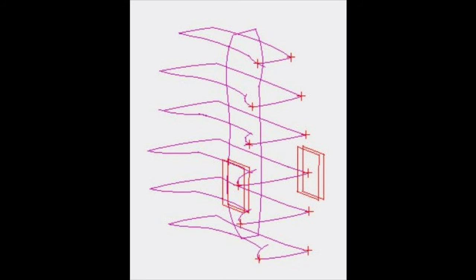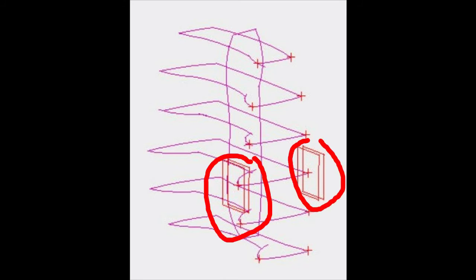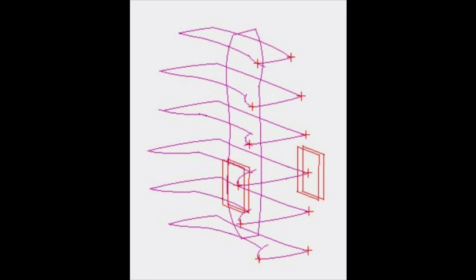First create the intersection point of the side curve and the back curve. Do the same on the intersection of the side curve and the bolster curve. Now create the bolster curve and the side curve. Create another plane parallel to the back plane through the furthest intersection point of the side curve and back curve.